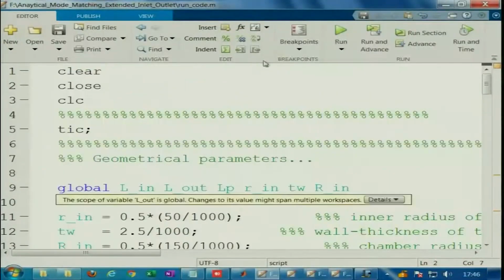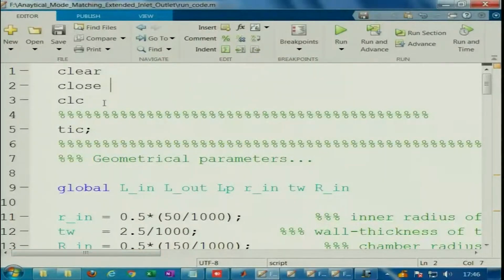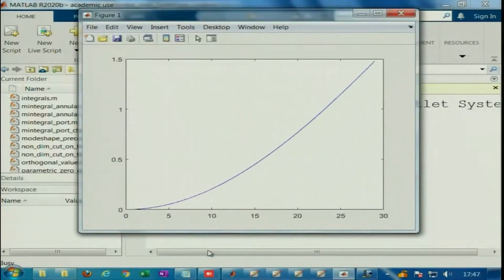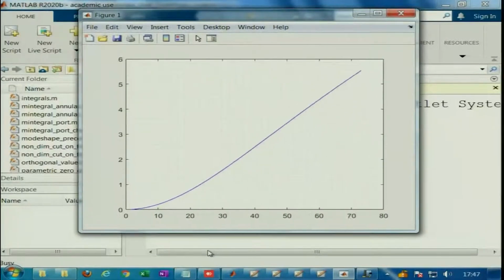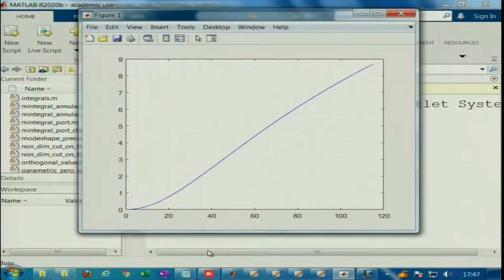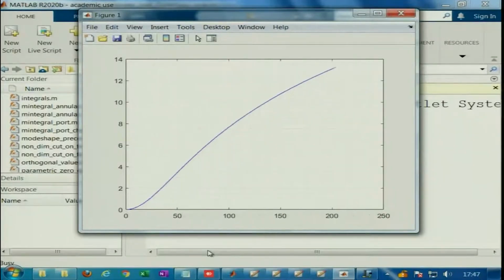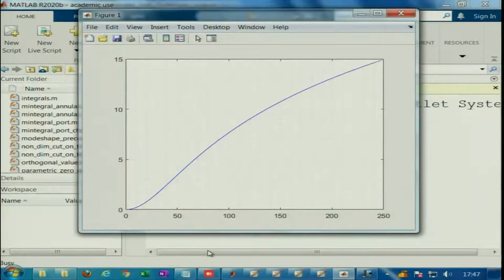Now, we are in a position to run this code. So, 2.5 mm is the thickness, and I have already done this. Let me hit the button run. So, let us see the kind of mistuning that we get just by considering the finite thickness, 2.5 mm thickness, which is not all that great. I mean, that is a nominal thickness you would usually encounter in all engineering applications. So, after pre-computing the modal integrals and the resonance frequencies and all that, we start with the live computation of transmission loss. We should be done as usual in the next couple of minutes or so.